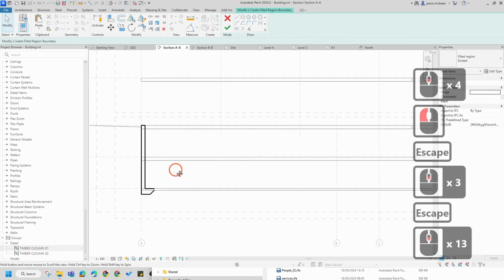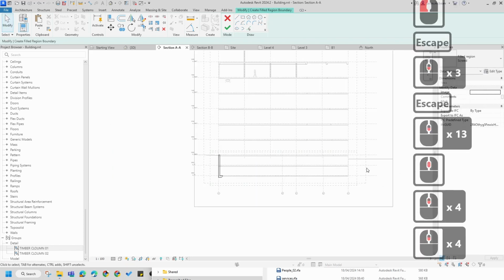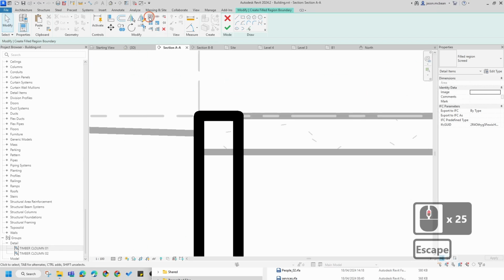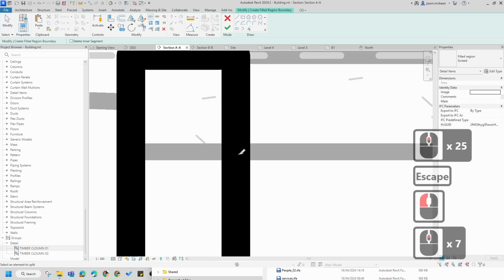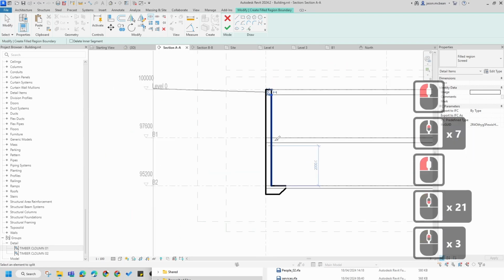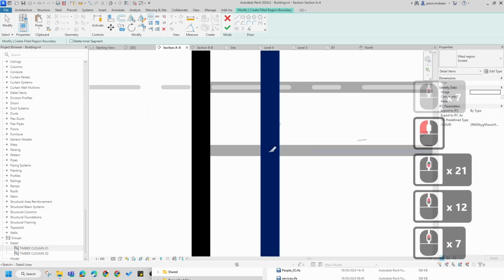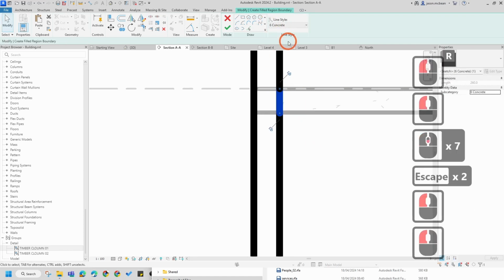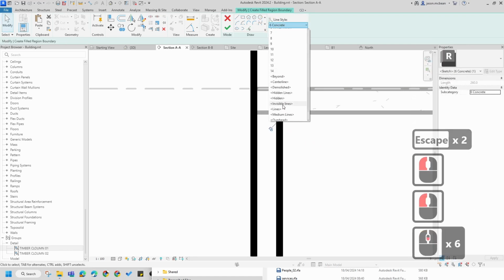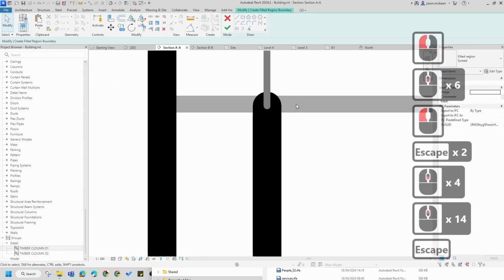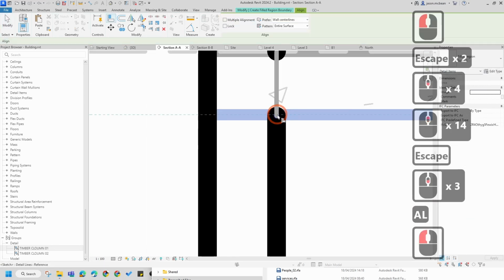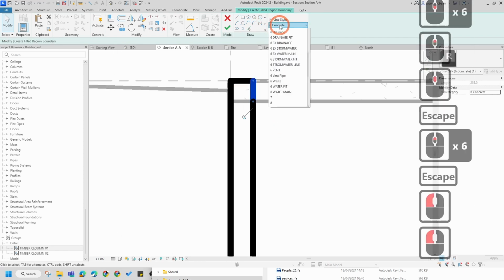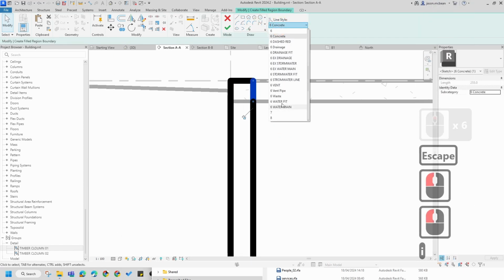You just need to bear in mind where your slab works. So section A, this is from front to back, so this will work like this in essence. You might have to split up this line work here in the middle. Split it up there, there, and there. These will need to become invisible lines. Remember, if you're drafting everything, this can become one bit of line work. Invisible lines.